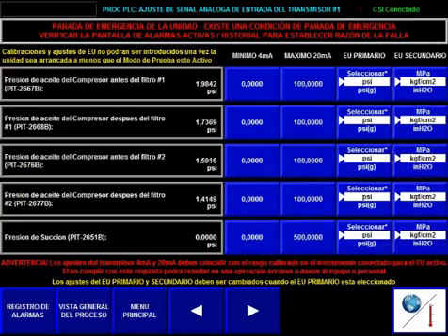Looking at the suction pressure, you can see a low of 220 and a low low of 265. These are Class P. Class Ps are armed and triggered in the compression stage, so they won't trip or set an alarm until you're compressing. The high and the high high are Class A, which means they will act at all times.